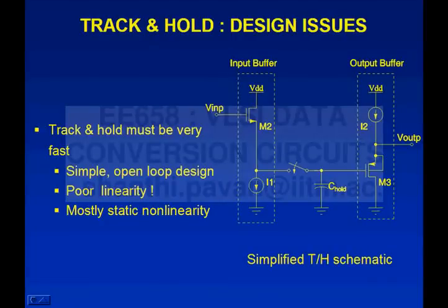So if you look at the IV characteristics of the MOSFET, in a simple analysis we say that it is doing this, and then beyond VDSAT it is going off as a straight line, and all that is bogus, you know that, right? That's just a model for us to analyze quickly. In practice, the slope of that line is varying with bias. So in other words, the output impedance of this current source is dependent on the absolute voltage here.